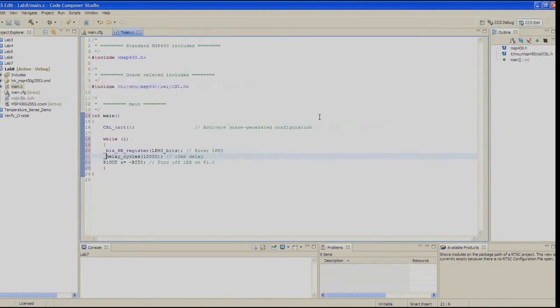So let's say the timer goes off, right? It turns the LED on. It lets the while loop run, which then enters LPM3. There's a 10 millisecond delay, so the interrupt is actually going to occur between the first and second instructions of the while loop. Then there's a 10 millisecond delay. We turn it off, we go back, we turn it off. That way we'll actually be able to see the LED blink here.